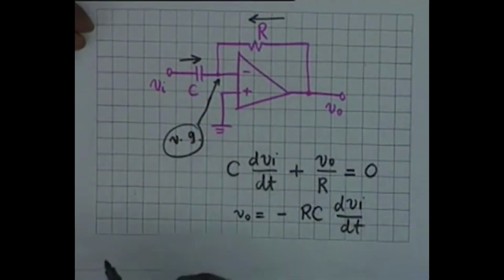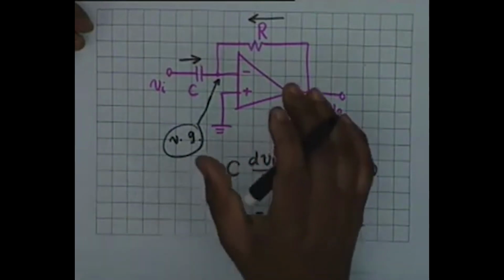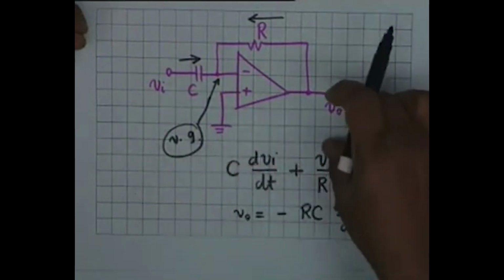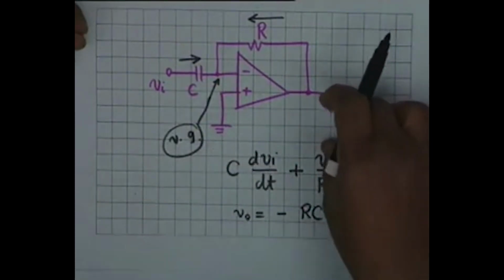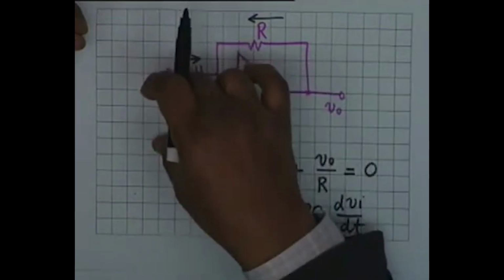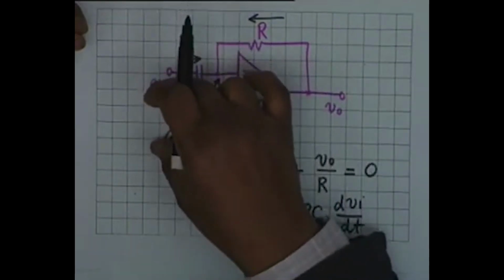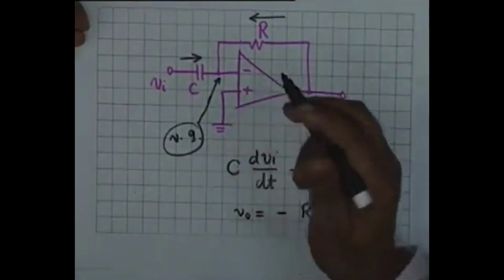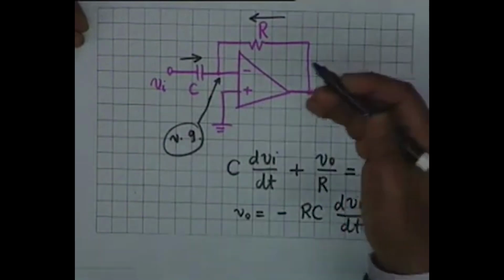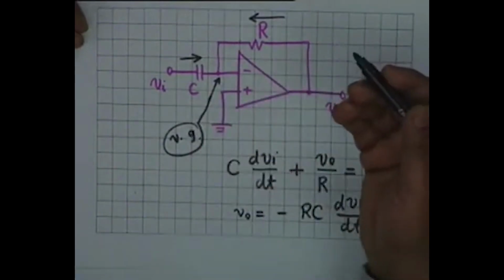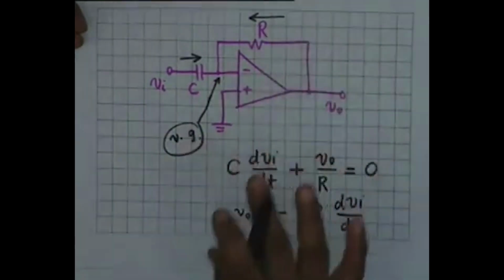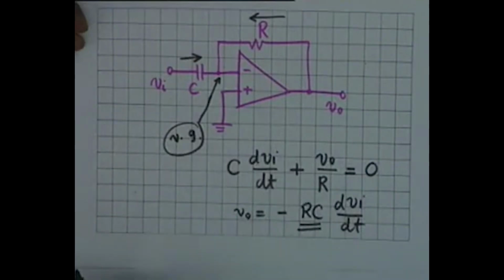It will increase it. You see, magnification or amplification, the term is used when the waveforms are preserved. That is, if the output waveform was of the same shape as the input wave, then the term amplification or magnification makes sense. Otherwise, if you are changing the wave shape, what is it that you compare? The two shapes are different, and therefore we don't say magnification. What I am saying is that the RC product now is arbitrary. It has no relation to the frequency or the time period of the input waveform. Alright?